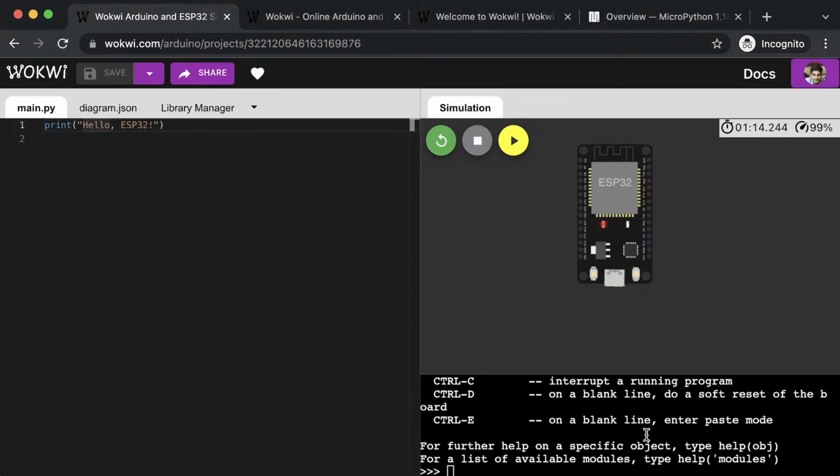It goes line by line, and that's a very basic difference between Python and any other language used for programming microcontrollers, be it C or C++. What happens is you write your code on your PC, the compiler compiles it and transforms it into binary code. Our digital systems can only understand binary. So it is converted into binary code, and then that is put into the microcontroller's flash memory.